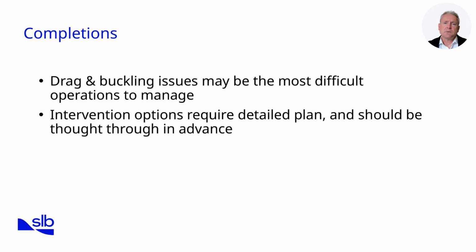Completions in ERD wells present some of the toughest operational challenges. Drag and buckling, which were already significant for drilling and casing, become even more critical when deploying completion assemblies. Long, heavy strings, such as sand control screens, packers, and liners, must be run into the well with very little margin for error. Often, completion operations require detailed intervention planning well before the drilling phase is finished.